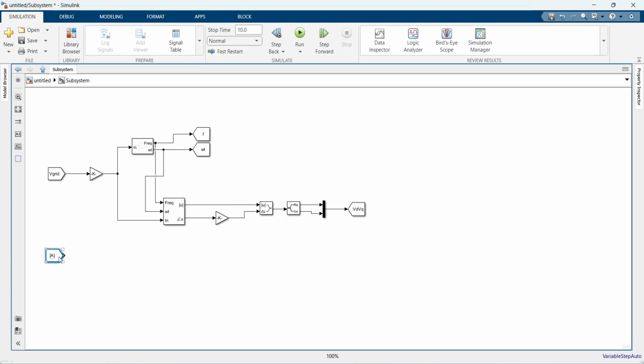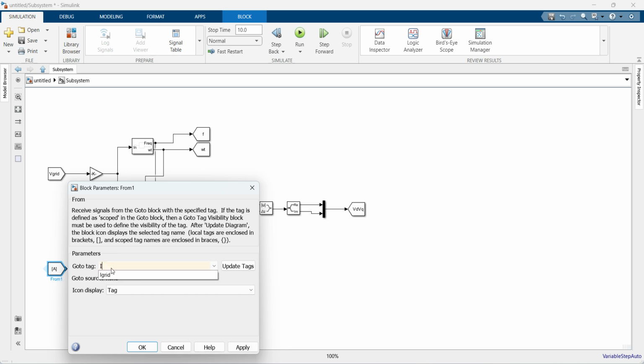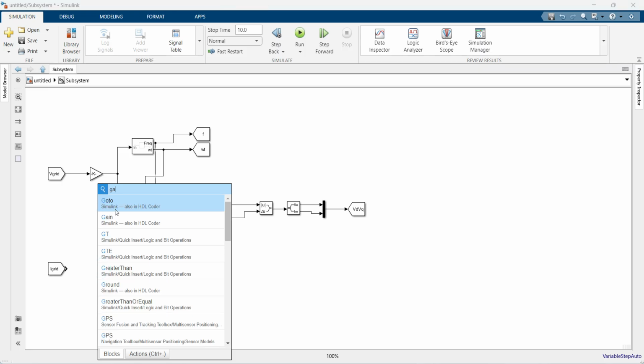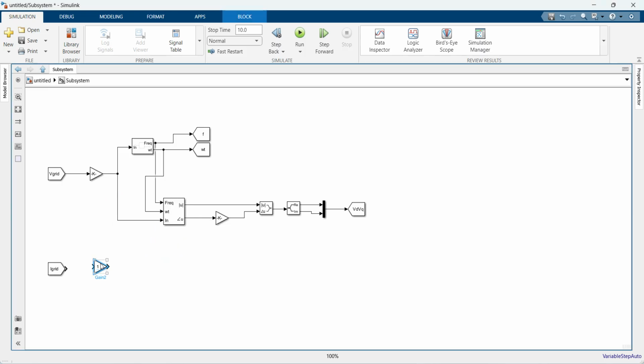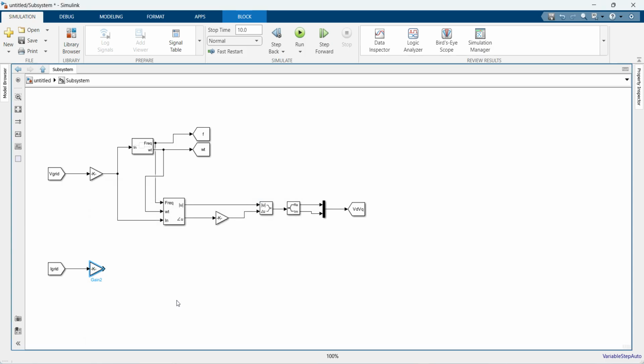I'm taking it from the block here, and it will be our grid current, I grid. Similarly, we have to convert this grid current into a per unit quantity, because we are dealing with a per unit system. It will be 244,000 and square root of 2. So this value will convert the grid current into a per unit quantity.